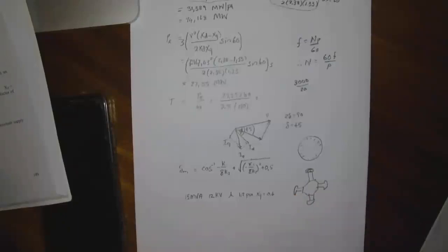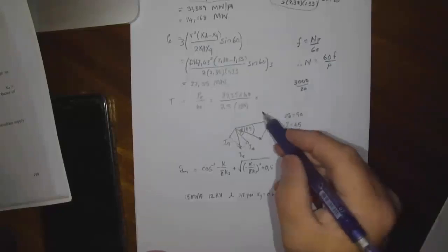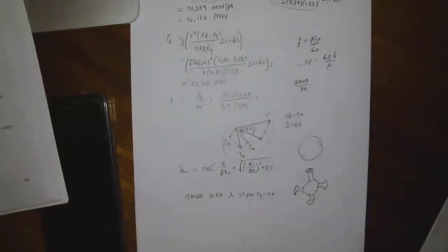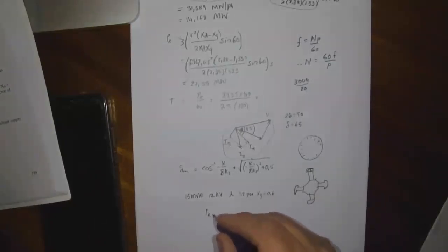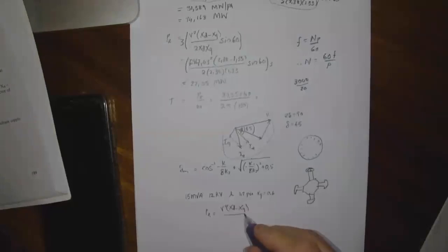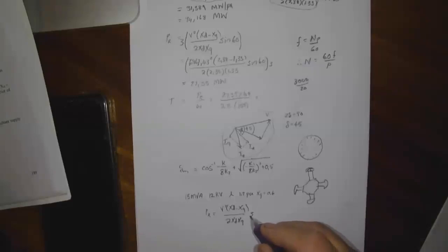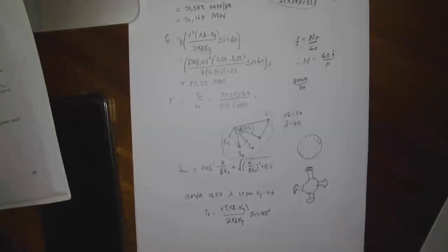The machine's load is varied to meet the following condition: maximum power with no field excitation. And then the question is to estimate the value of this power, the armature current, and the power factor of this condition. That's basically what you just discussed here. Because we don't have anything else, we're going to say that the power is the reluctance power, which then will be V squared (XD minus XQ) over 2 XD XQ, and it will be at 45 degrees because it's doing maximum power at that stage.